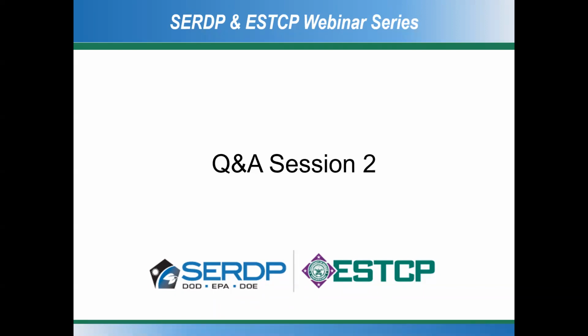Okay, thank you. And I think we have one last question on the second part of the presentation. You had noted that the desired MUST elevation above the seafloor is 5 meters. Can you comment on how close the tow body can be to the seafloor and still get the data? So the tow body could fly at a much lower elevation off of the seafloor. There's two complicating factors. The closer you get to the seafloor, the less of a footprint of the sonar on the seafloor. So now your track spacing has to be smaller to cover a large area.